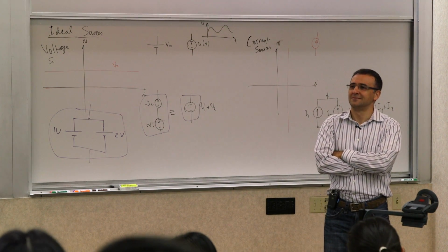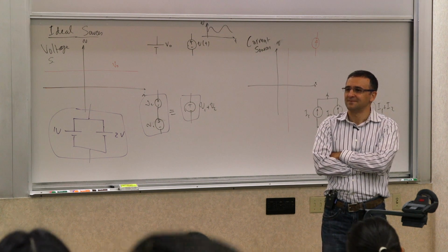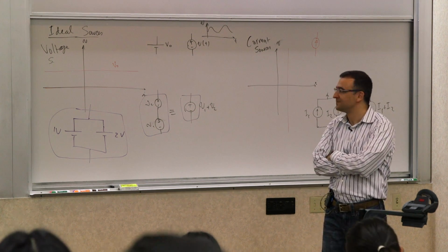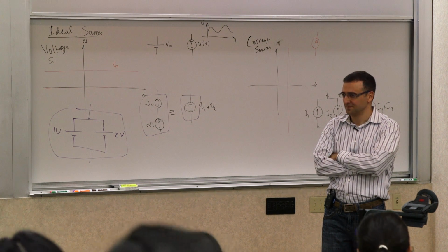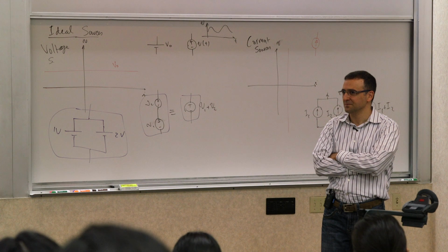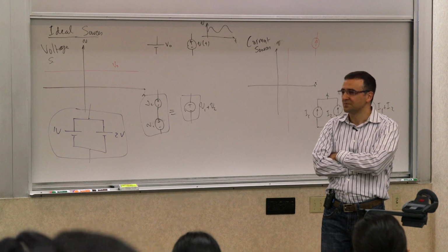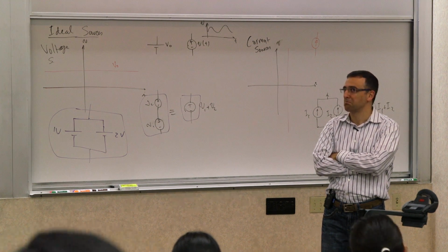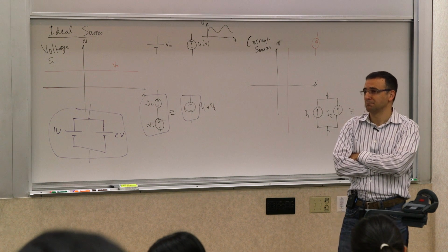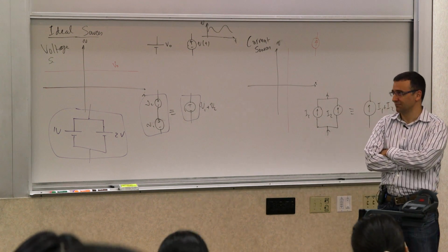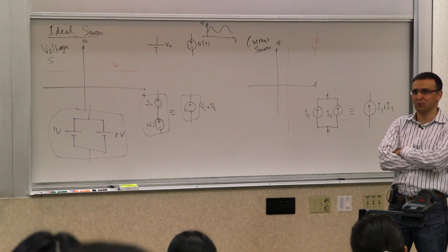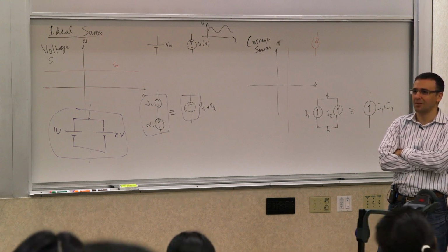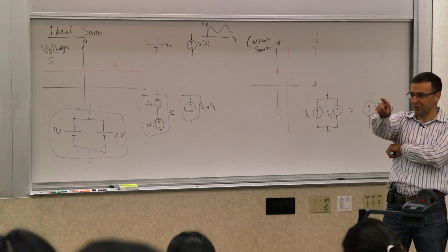Will. Okay. Well, the problem is that you have a short circuit on both the top and the bottom, and the IV curve of both voltage sources is trying to establish a different voltage across the short circuit. But the short circuit can't have a voltage across it. The voltage sources are going to start competing. The 1 volt source is going to sink a lot of current, the 2 volt source is going to provide a lot of current. Sure. Yeah, there's some sort of a problem. You're observing a problem, right? Good observation. Hold that there.